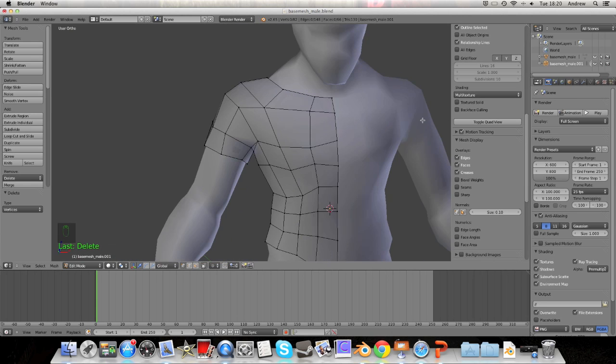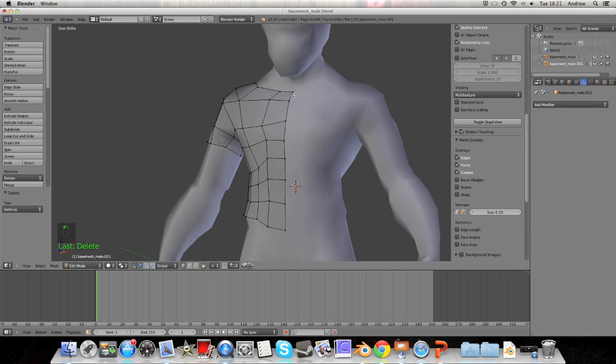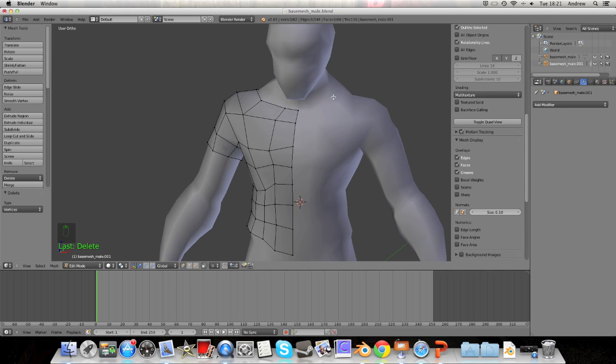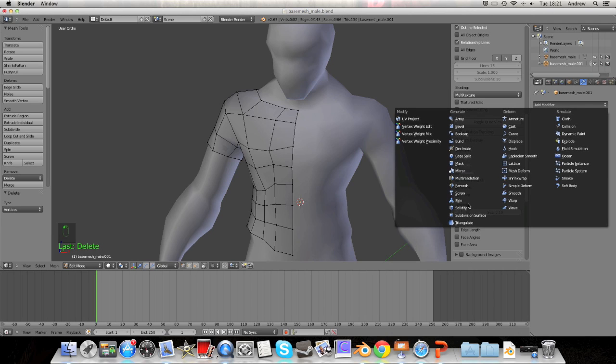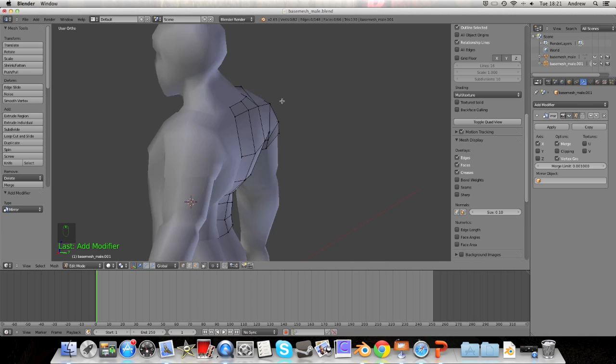And what I'm going to do is press onto the modifiers. We can do this in edit mode, although we can't apply it in edit mode. And I'm going to go to the mirror modifier. So that's worked out that I want it on that axis, but if it's gone wrong for you, then go to the axis setting here, change which axis you want reflected in, and hopefully you'll find one that works.